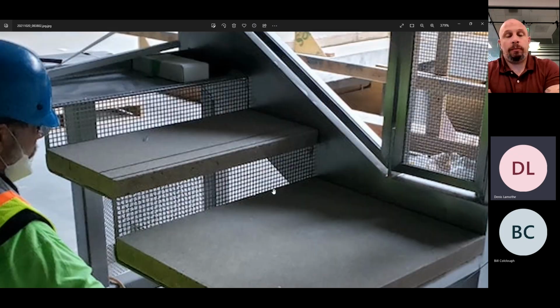The other thing to consider with precast terrazzo is the likelihood, and apparently this is something of a common theme that we've experienced on some of our jobs, that if you were to look end to end on a poured terrazzo part or even a larger panel, it's not uncommon to see them twist. One end might be flush, and at the other end it'll be twisting slightly upwards.